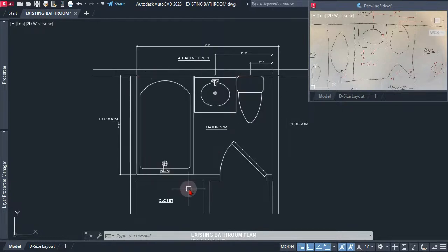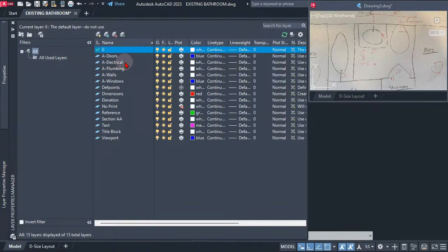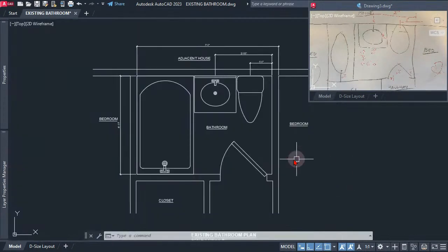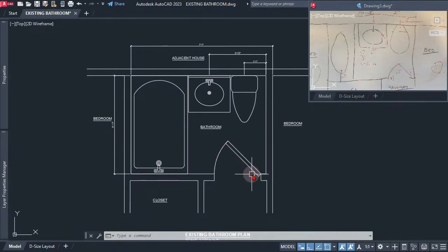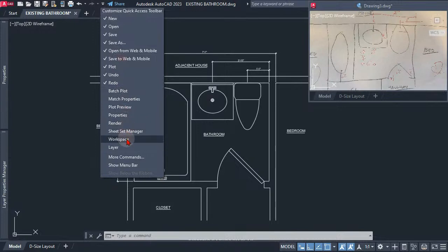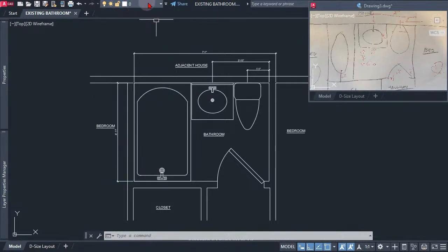So let's open the layer palette, and we can see that AutoCAD, when we pick the template, it's already giving us some layers. If we need a layer, we can simply click this icon and create one. That's not a problem, but we already have some. So we're gonna reuse some of these layers. Now, here I will need my ribbon, right, to pick my layers, but not really. Let me show you. What we can do is expand or click the quick access panel. This is called the quick access, and we can pick the layer option, so that way we always have our layer over here.